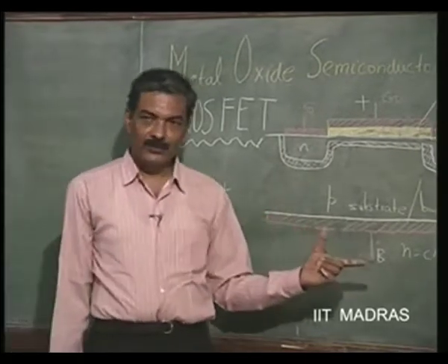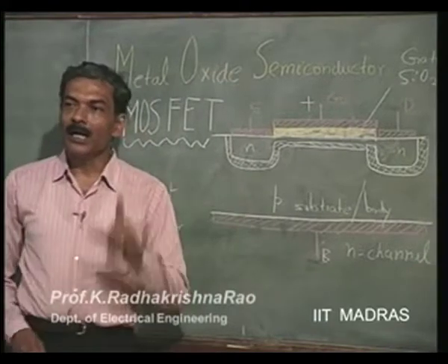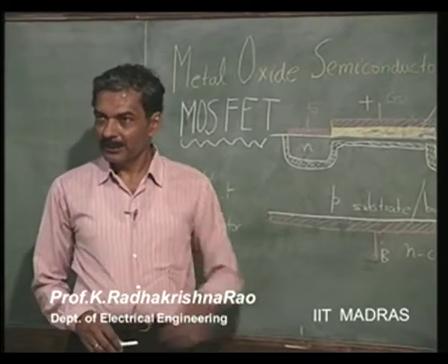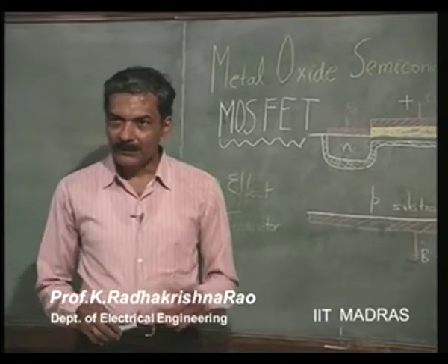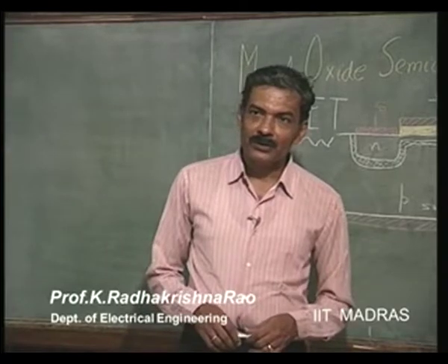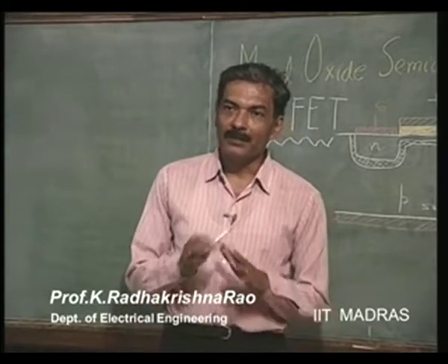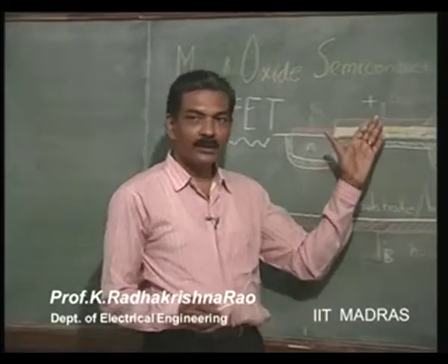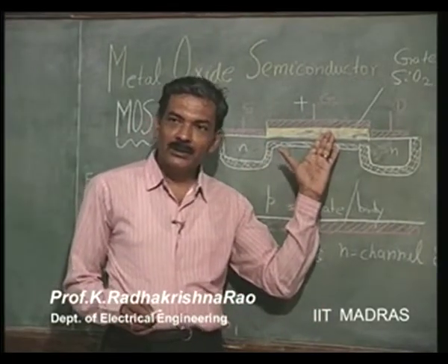These devices are initially not conducting. When the gate is open, or not connected to any voltage, or connected to 0 volts, all these devices are off. They can become on only after crossing the threshold voltage.